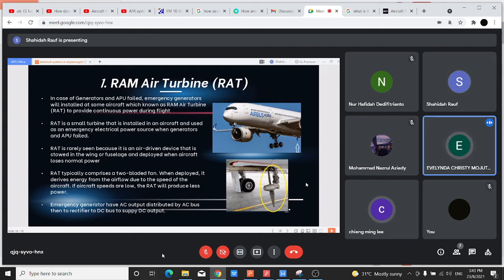When you start number one engine, number one will power half of the aircraft electrical system. The APU will power the other half. Once you start number two engine, then number one and number two engines will power the whole aircraft, half and half. Then the APU is just sitting there, cut off. In case there's any failure, the relay will connect it online.